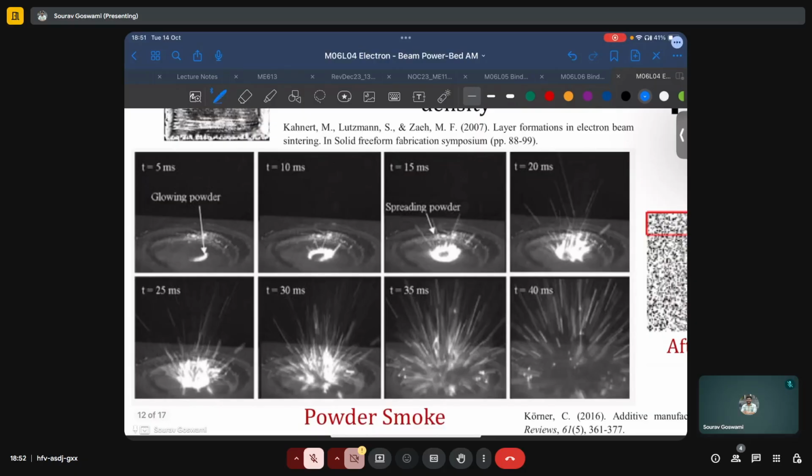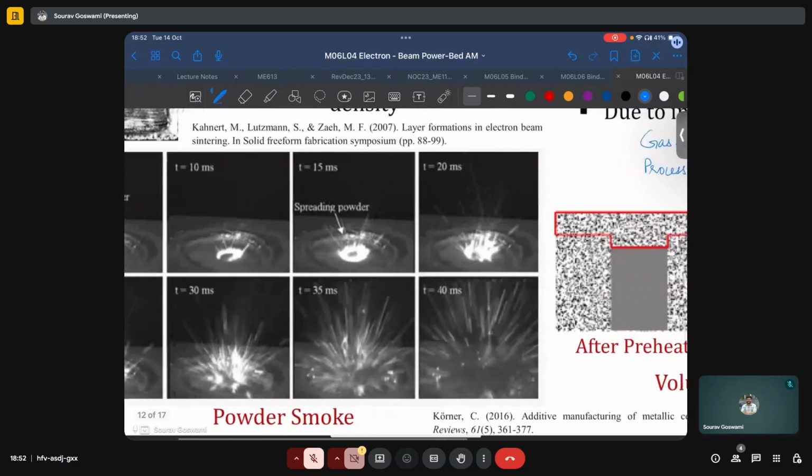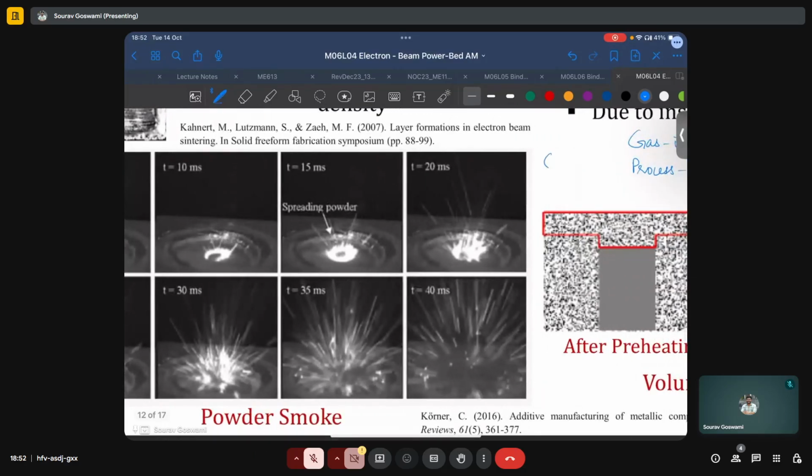What is the reason for this? So, if we are assuming just a plain spherical model of powder particles, then in a powder bed, they will typically be connected to each other only at these small regions of contact across powders, which will be a non-conformal region, typically a surface, but still a very small contact. And we know that electric resistance is inversely proportional to area. So if the area of contact across two particles is very small, the electric resistance between them will be higher.